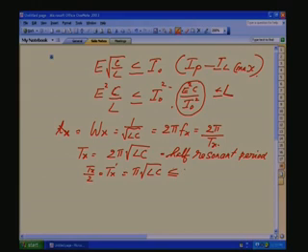So, 10%, 0.1 of T on minimum. Okay. Let us square this one. That means pi square into L into C is less than or equal to 0.01 into T on square minimum. Okay.